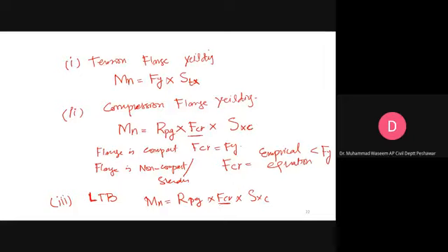If the lateral bracing is less than or equal to Lp, there will be no LTB problem, okay?